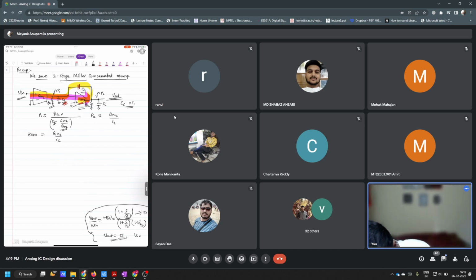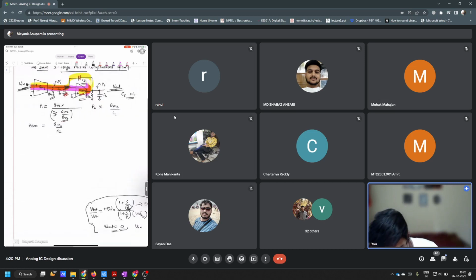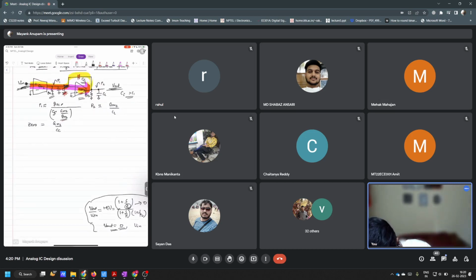So first of all, from the input, which is here, we have the same path up till here, right? Up till this, everything is the same for both the paths. But right from here, we have these two branches which are bifurcating, and then they are again combining at the output. Okay. So any signal, any current that passes through this CC and through this GM2 will have different phase shifts. Did you understand this? Yes. Why should they have different phase shifts?